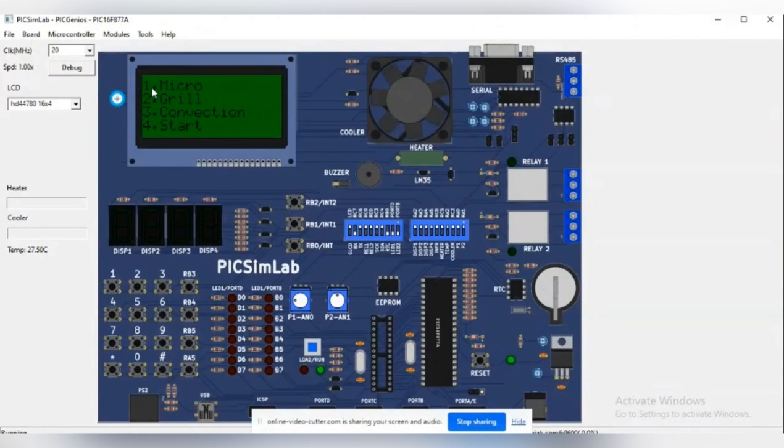Now let's press 1 on the matrix keypad. It's showing power is 900 watt. It's asking us to set up the time. This is used to set the seconds, and this is used for setting the minutes. Let's set 15 seconds for a sample. Asterisk is used to clear what is entered. It's now set to 0. Let's set it to 25 and enter using the asterisk on the matrix keypad.